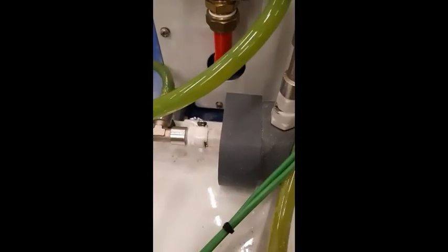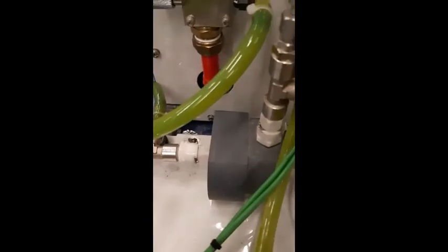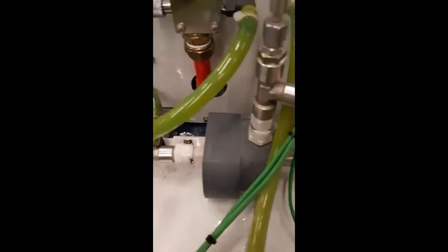So today's experiment, we do first the parallel flow. What is parallel flow? Hot and cold flow in the same direction. So how we set it here: the hot water comes from here and goes this way, and the cooling water supply is from here, comes here and goes here. So what we see is hot water and cooling water coming through the same direction of this pipe.